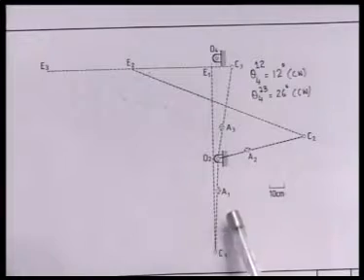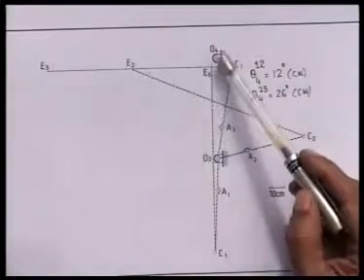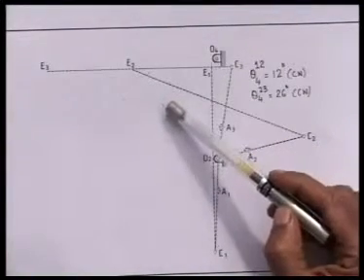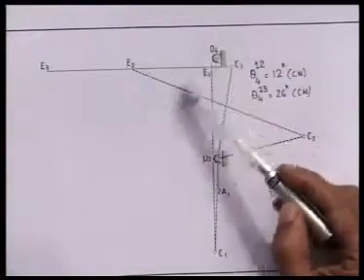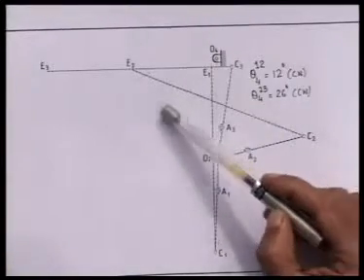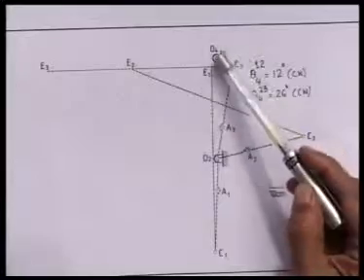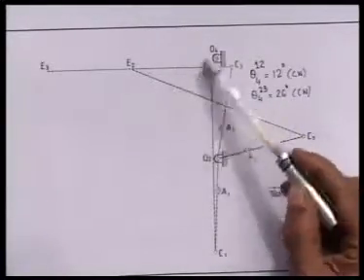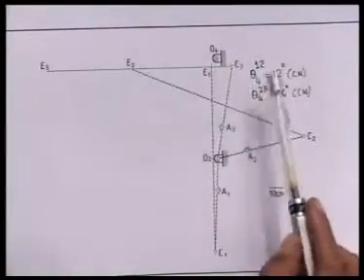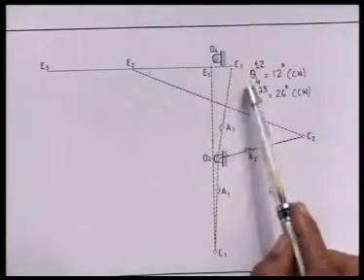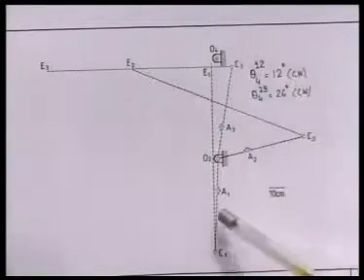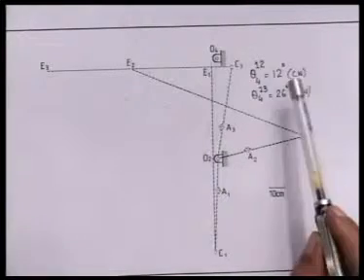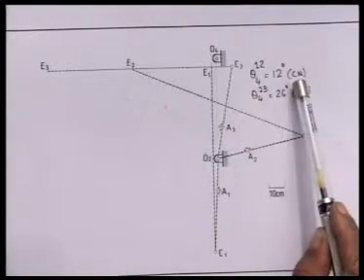It is also specified that the fourth link, which is connected to O4 up to the point B where there was a second order hinge, 3 links are connected, that point we call B. This O4B is the link 4, and it is also said that the rotation of this fourth link, theta 4 1 2, from configuration 1 to configuration 2 is 12 degree clockwise.